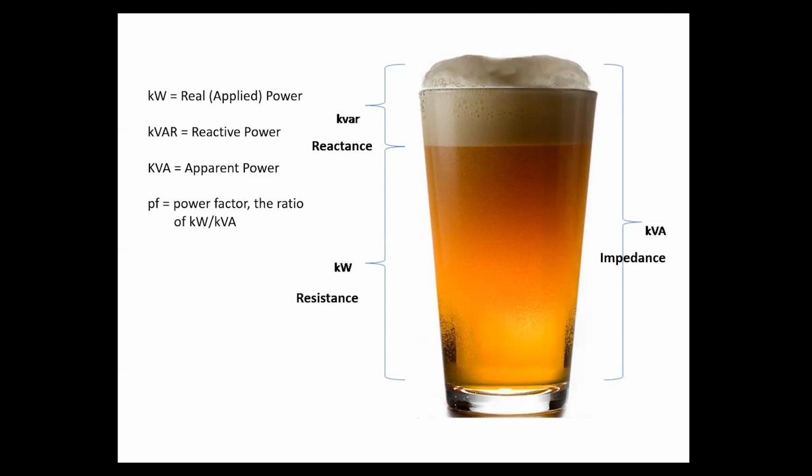Well, what we're dealing with in the Smith chart is looking at how reactive impedances affect the signal that's going through the line. Analogous to the real beer, to the real power, is resistance. That's what we want. We want the antenna to be totally resistive, because that means everything goes to the antenna and something good happens with it.